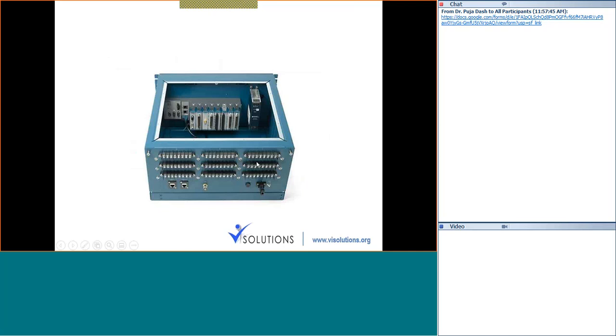You'll make the connections from the voltage transformer, current transformer, to this system, and this will be connected to your CompactRIO platform, and internally it will have these algorithms which will calculate the voltage required, and with that data it will be able to make some decisions, maybe synchronization decisions, and this data will be sent to some other centralized location which will make the ultimate decision.